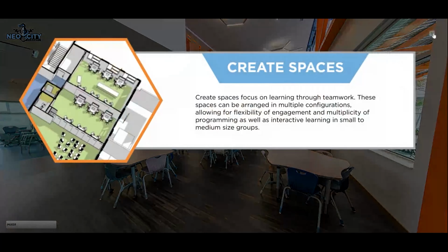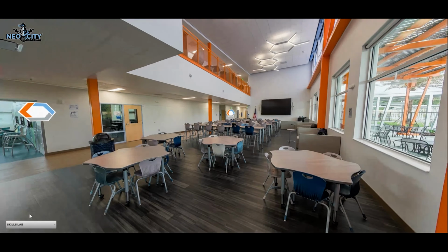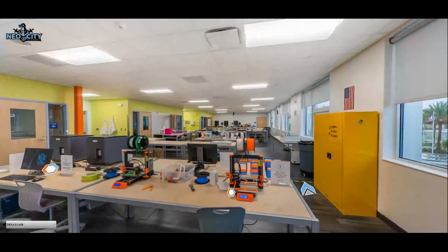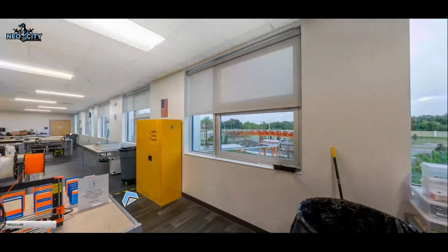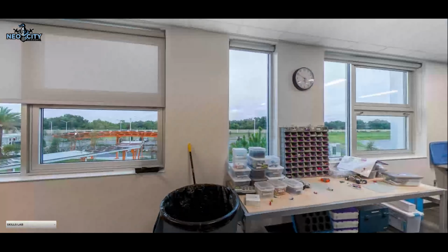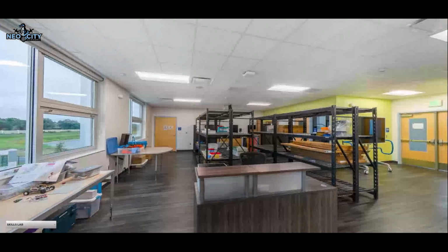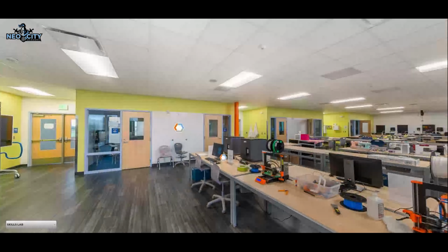But without the dashboard, sometimes it's really hard to find these things because you're not seeing live data of what's occurring. And so we really recommend as we do projects, we break it out with lighting and plug loads and HVAC loads, and you can look at that and the total, and you look at the generation. And another thing we saw, that it wasn't generating enough. And we're like, why isn't it generating enough? Well, we ended up going to the supplier. They went out on site and they found out there was a maintenance issue that needed to be dealt with, and that's why we were low generation.